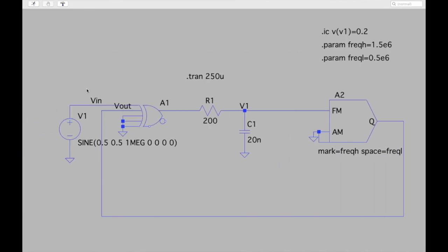To understand these things, we need to model the behavior of this PLL from the control system perspective. We need to get the S-domain model of this PLL and see what happens when there is an abrupt change in the input frequency, how the output is tracking, and why the PLL is taking longer to settle when I increase the capacitor.